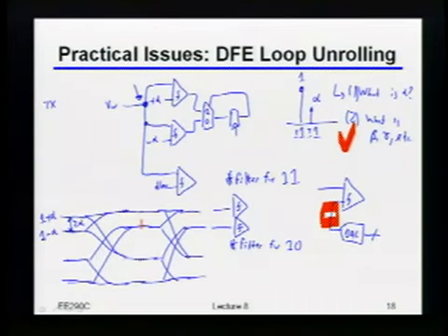Yeah. What if you use two comparators to get the D plus alpha and minus alpha, and then just pick the correct one to do the error calculation depending on the data? Well, but that's the unfortunate problem: with these two thresholds, 1 plus alpha does not put me at alpha, right? And the threshold I need for this one is plus alpha or minus alpha. So there's no analog level at plus alpha or minus alpha anywhere, right? Do you see what I'm saying?